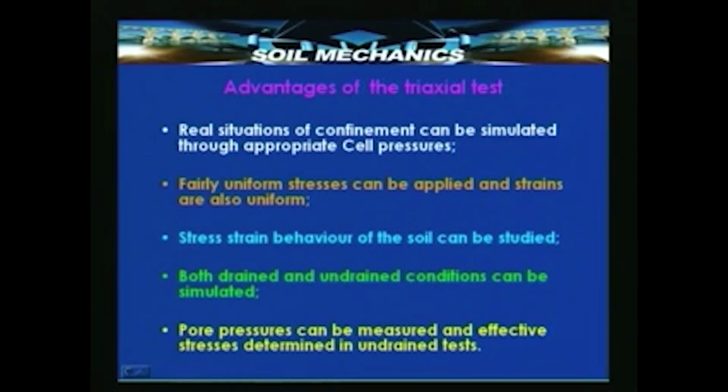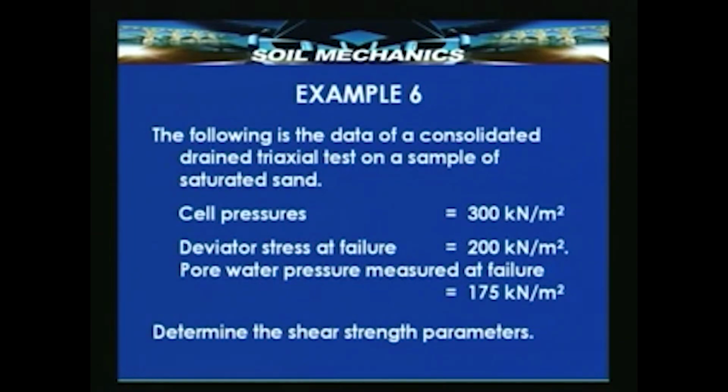kind of effective stresses are mobilized during the test, and the shear strength is a direct function of the effective stress. Therefore, knowledge of the effective stress is very necessary, and the triaxial equipment can really help you to get that. Let us quickly take a look at some examples.